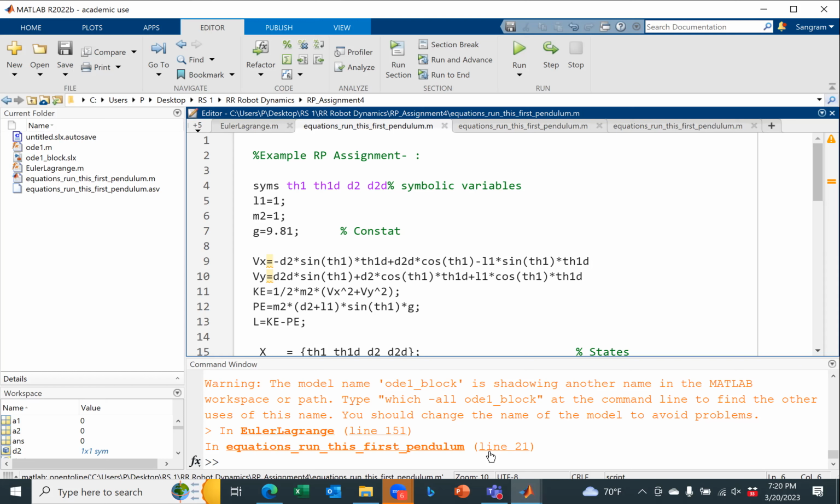We'll talk about it in the next class. If you have a 3-dimensional object, you have something called a 3x3 inertia tensor. As long as you consider the centroid, the off-diagonal terms of that inertia tensor become 0 and your problem becomes very simple. I will take a few examples and show you how that problem simplifies. So bear with me.